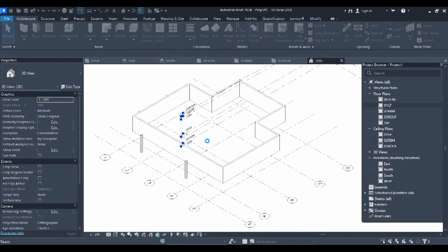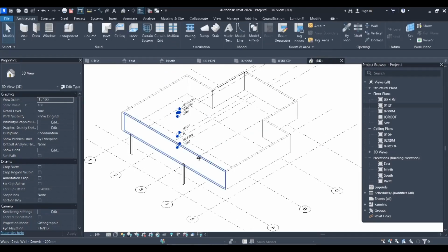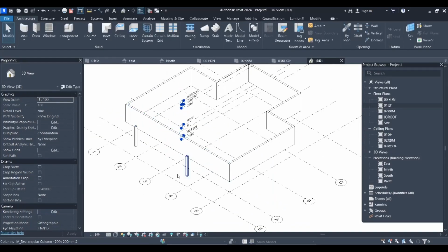So I was explaining on the details, the kind of view details that you want your 3D to see it at the level of your detailing. So detail level, fine, medium. So from there, the next box, now this is the most important box for 3D. You can view your 3D in wireframe, hidden line, shaded.